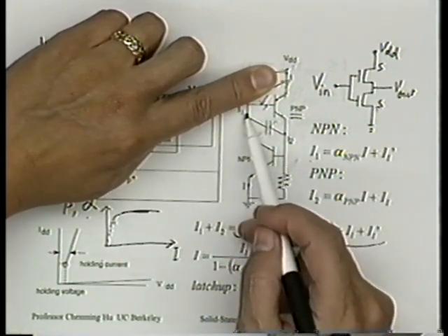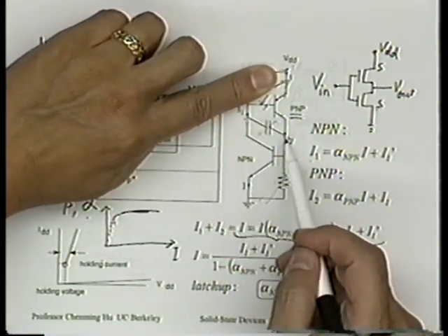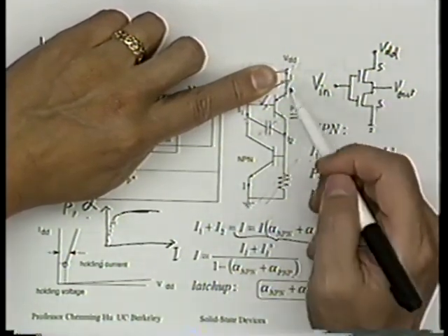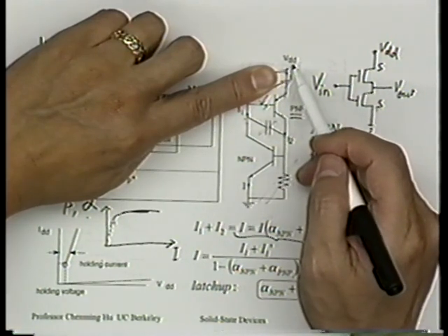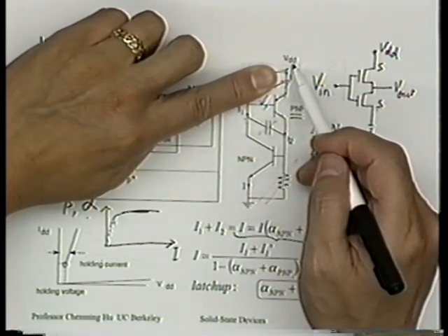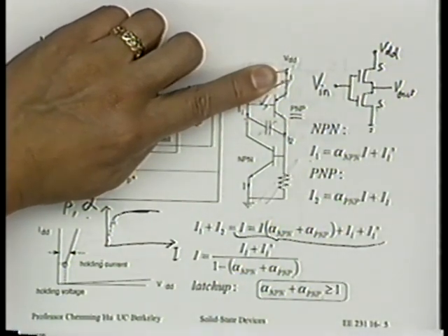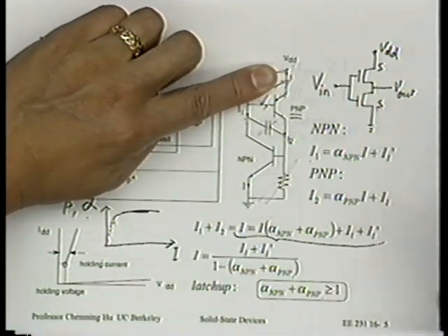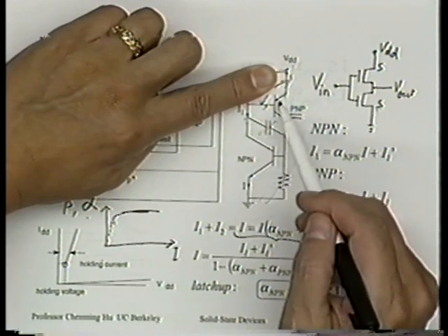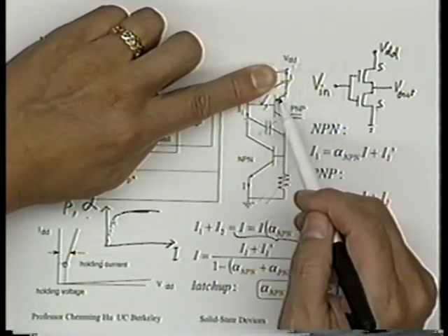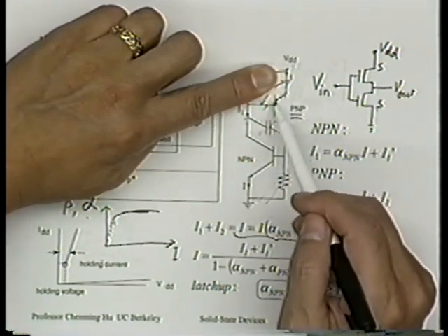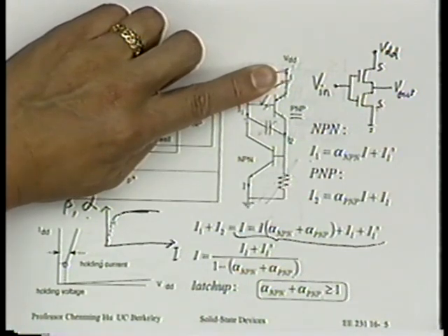But because this junction has large capacitance, is that right? Finite capacitance. So when I suddenly apply this VDD, for example, I just plug the PC board into the slot with the power on. Let's say it's hot plug-in, suppose, right? Then there will be a large transient current flowing through this base and emitter junction. Do you see that? Yes?